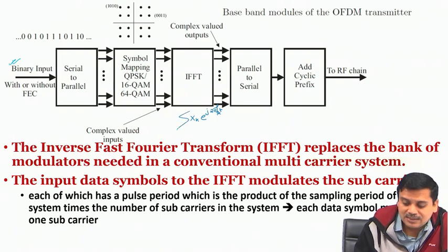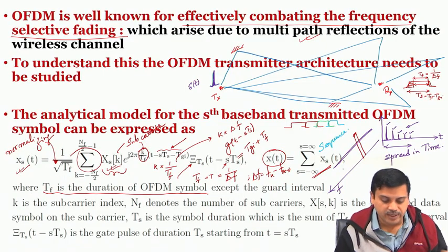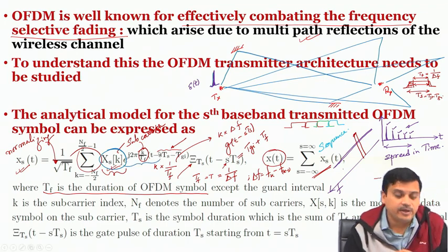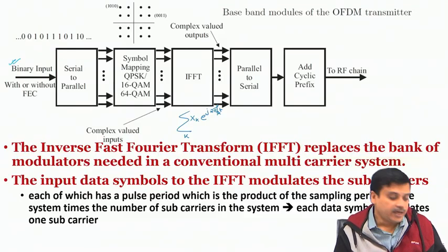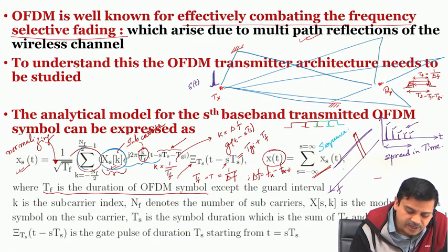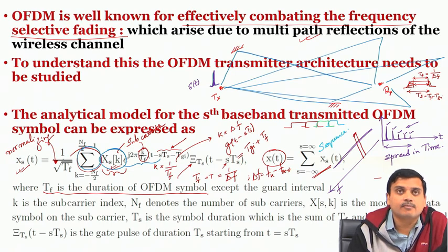And there is a sum over all these different subcarriers. So, we just take a look at this expression. These are the constellations and these are the carriers, all right. That is what we have over here, and these are happening in parallel, that is why we have this kind of a summation. Okay.